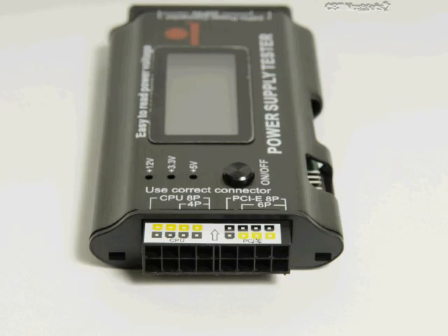And then we also have, on the opposite end of that, our CPU connectors here, which can be 4 or 8 pins, as you can see right here, or PCI Express connectors, which are 6 or 8 pins. My particular ones are 6 pins. Anyway, if I have the power supply on and the motherboard connector connected to the motherboard, then I can connect these on the side, like the CPU or the PCI Express ones. I have to have the power supply running in order to test these.